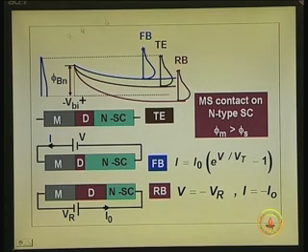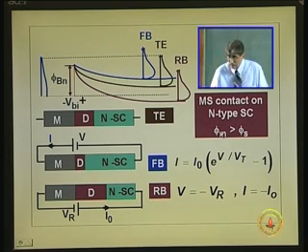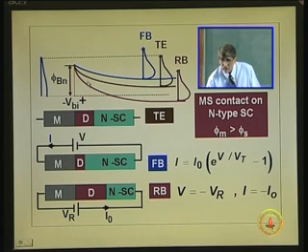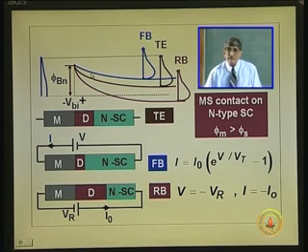So, here, you can see that in the thermal equilibrium situation, you have got the electrons transferred. We are talking of a case where phi m is greater than phi s. Going quickly through that, the electrons have got transferred from the semiconductor to the metal, leaving plus charge on this side, minus charge on that side. That is the built-in potential. In fact, from this end right up to this barrier tip, that is the built-in potential.